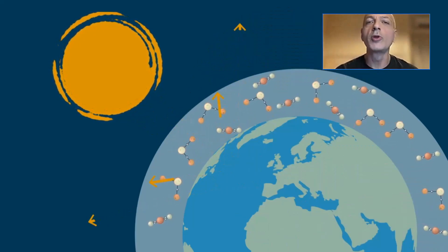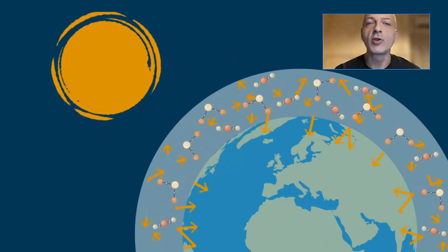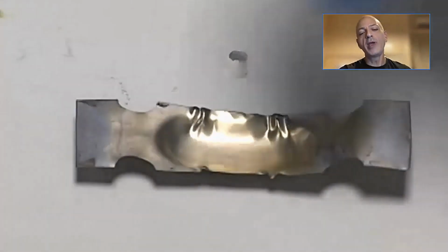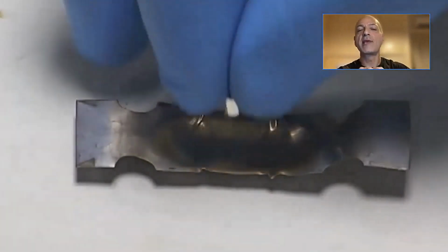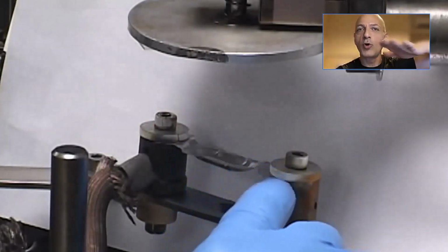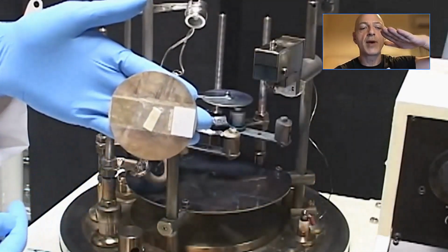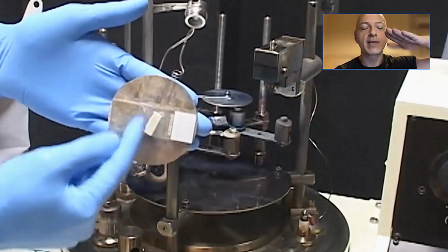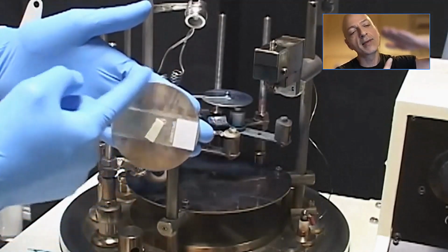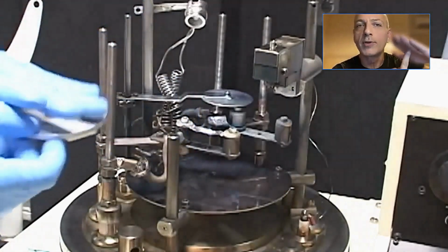We have a lot of molecules between 2 points, 1 centimeter apart. So if we evaporate something, for example, let's say copper or silicon, and we want to make a thin film of it on a substrate on top, then when the atoms come out, their energy will be impacted every time they hit an atom, and by the time they reach the substrate, they will be totally cold.